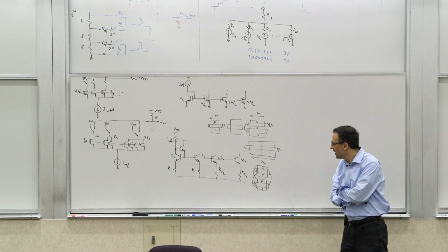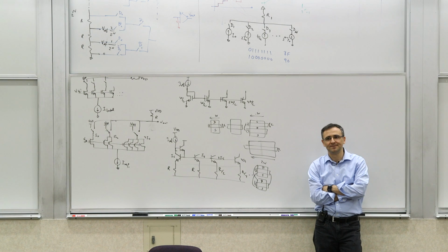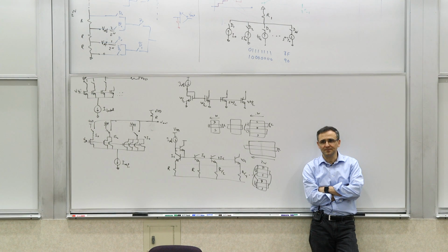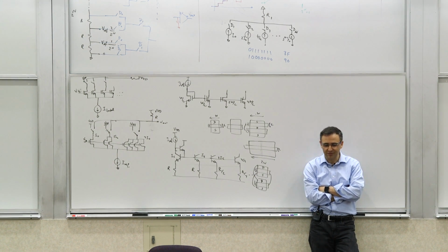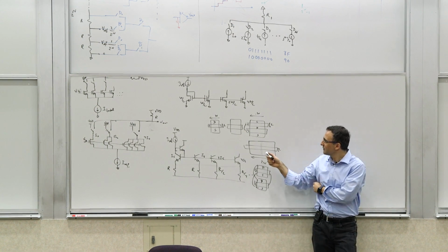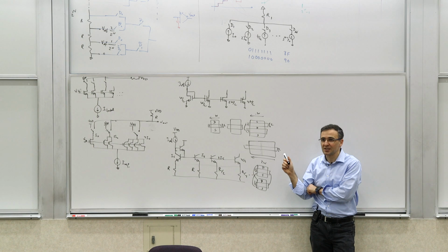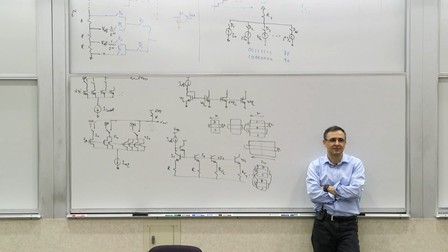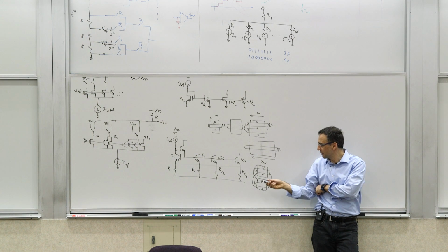But, okay, so why do you prefer design 3? You could interleave the various fingers between your different current sources to try to counteract gradients. That's a nice secondary argument, and we will get to that. But even primarily, which one of these has a better chance of carrying exactly twice as much current as the other one? Number 3, right?